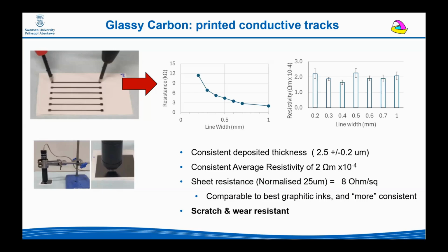And what is another advantage? Once cured and sintered, it was extremely scratch and wear resistant. We broke first the substrate, that was alumina, before our glassy ceramic carbon. Fantastic. We demonstrated some printed tracks, and of course we want to select some demonstrators.